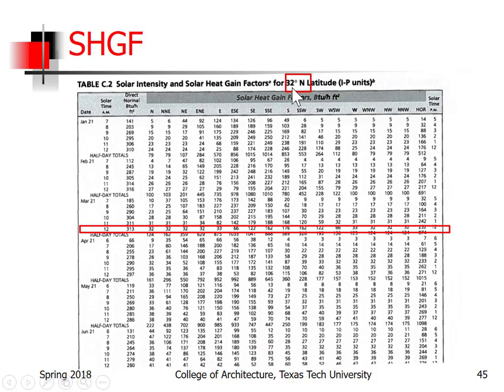You'll notice these tables are about 4 degrees apart, so it's all dependent on the latitude that you are at, because that affects the angle of the altitude of the sun. How you read this chart is, you'll see right up here, does the glass face north, north-northeast, northeast? This is of course in 15-degree increments.